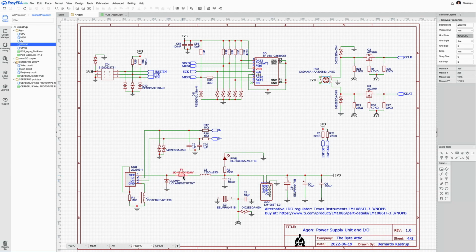This is just a fuse. It's a solid state fuse, so when it opens, you don't need to replace it, because once the excess voltage, or the excess current in this case, gets reduced and current goes back to normal, then it reconstitutes itself. So it's not something that you ever need to replace, but it works as a fuse in the case of excess current. This works in the case of excess voltage. And this is just a little coil, a little bead, to stabilize the current.